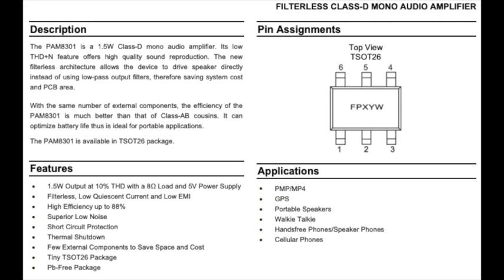It's now considered NRND, meaning not recommended for new design, even though right now there are 15,000 of them available on the DigiKey website. It appears that it's been superseded by the PAM8302 and the PAM8304, even though they're not directly pin compatible. And it would require a redesign.